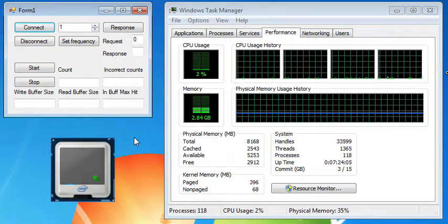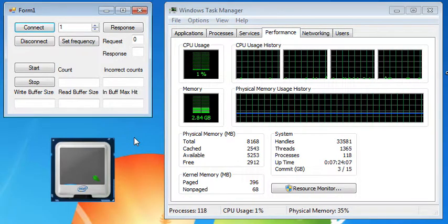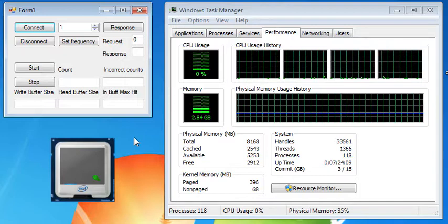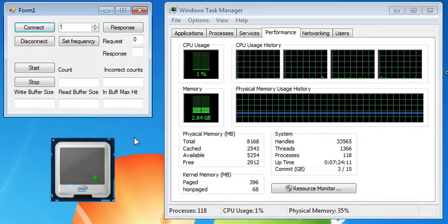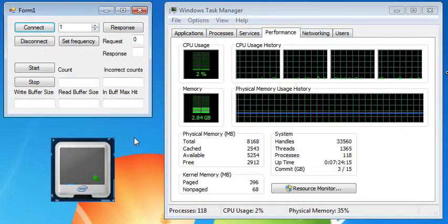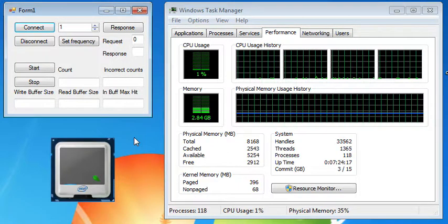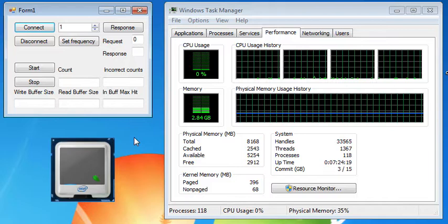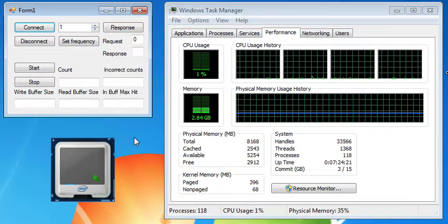Okay guys, what we have here is the serial speed test for our quadcopter command center. We had issues previously with the aero-quad software and our modifications sending information at more than 10 Hz. The issue being that the PC event handler would only read the first line because we were using the serial.readline function from the .NET library.